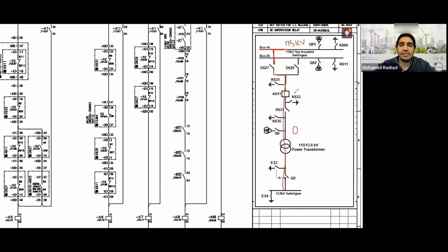Both had 115 kilovolts. Are you sure that both are exactly 115 kilovolts? Are you sure the phase shift between them is 0? Are you sure the frequency difference between them is 0? Of course not. You might say, just do a synchro check, and then close the breaker, close the disconnector.